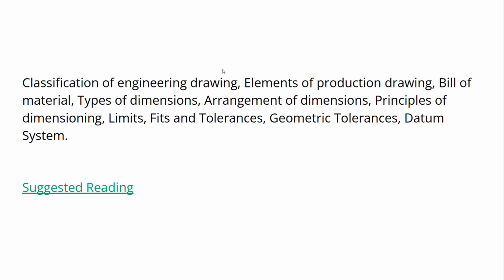Classification of engineering drawings, elements of product drawings, bill of materials, types of dimensions, arrangement of dimensions, principles of dimensioning, limits, fits, tolerances, geometric datum system. Limit means the maximum and minimum permissible size of the part. Tolerance means the difference between these two limits, indicating allowable variation.